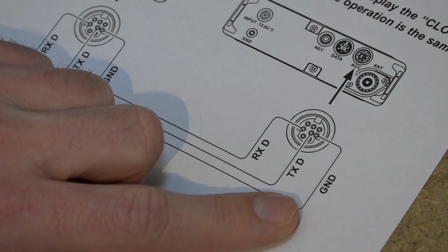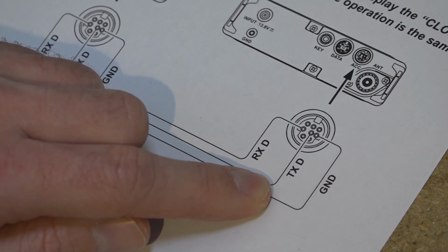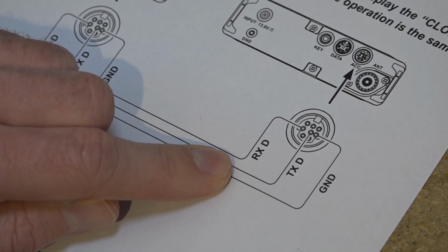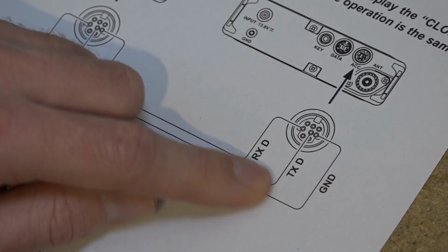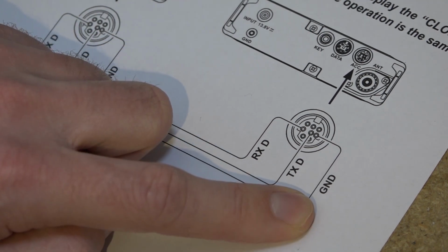Great. And I'm also looking at the manual for the radio. This is on the page, it says cloning, but it's actually got the pin connections that we need for this lead. So on that MIDI DIN, as we look at the back of the radio, we're going to need to make 3 connections. We're going to need to connect a ground, which will connect to the shield of the cable. Transmit data, that's data coming out of the radio when it sends information to the computer. And receive data, which is when we're sending information from the computer to the radio. So we'll connect those two to the 2 main conductors in the cable and ground to the screen.